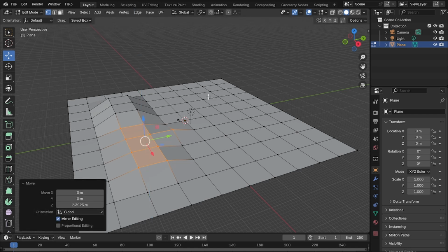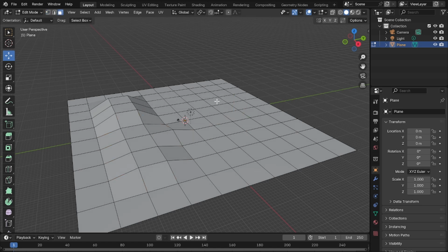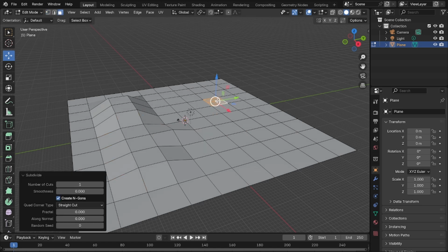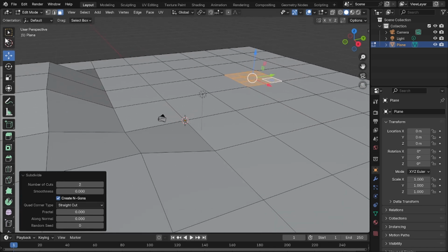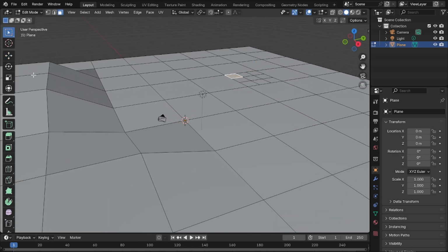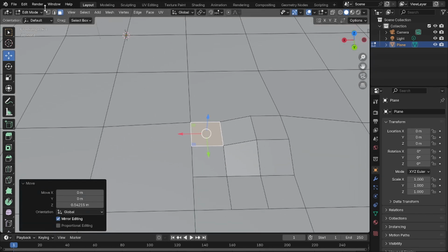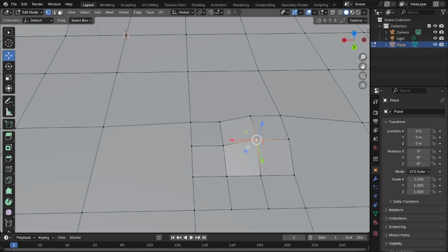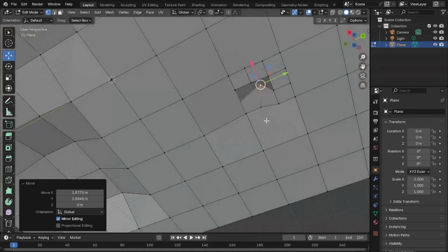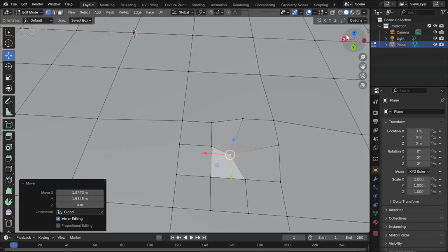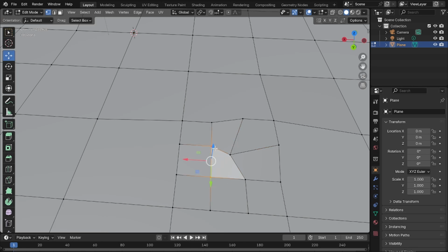A key point is that the vertices on the corner of each of these 10-meter squares should not be moved in the X and Y direction. However, if you need more detail, feel free to subdivide these planes and then you can adjust each of those individually. And actually, the vertices within a 10-meter square can be adjusted on the X and Y coordinates without disturbing the chunking. This gives you an ability to make quite a detailed landscape.